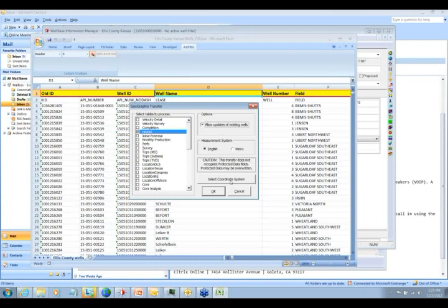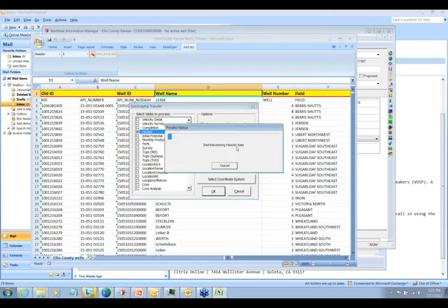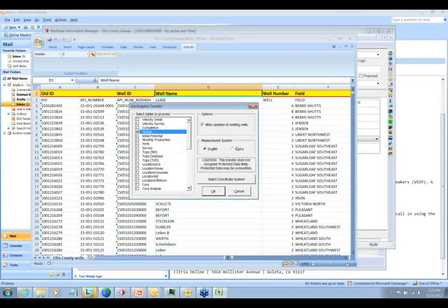So for instance, if the location data of the wells are in GeoGraphix lat long NAD 83 or NAD 27, you can select that, and it will automatically be transformed to whatever your project coordinate system happens to be. So we'll just go ahead and bring that data in and transfer the header data in.